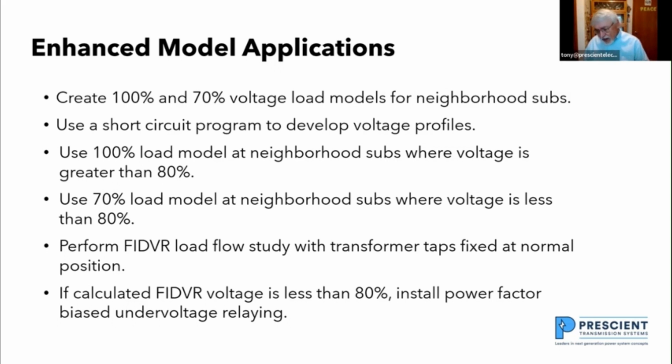If I've got motors accelerating, that would indicate the power factor is poor. So say if the power factor is 70% after 10 seconds, that says motors are still accelerating after 10 seconds. And what I would do is shed load at that substation. And I'm shedding load to try to prevent a wide area grid collapse.